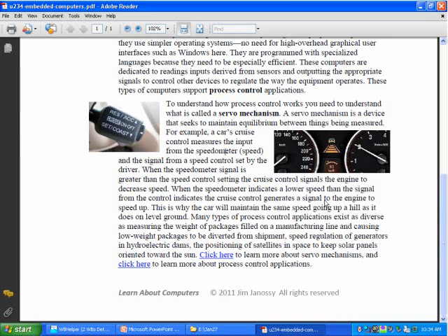In the old days, let's say with a steam engine, this was done mechanically with what was called a governor. So you could set the governor so that the engine would go a certain speed, and mechanically it would cut back on various things if the engine overspeeded. But now this is done electronically, and it's done more reliably this way because the sensing devices can be more precise, and the computer program can be set in such a way, or perhaps varied, because the control here is actually varying one of the inputs, so you can vary where you want the setting to be, and the equilibrium maintained by the embedded computer program, the embedded computer acting like a servo mechanism, will control this.